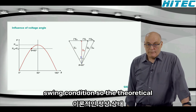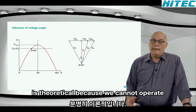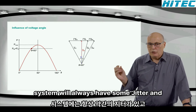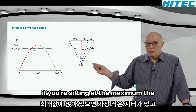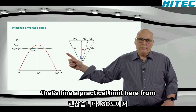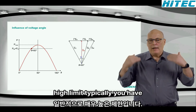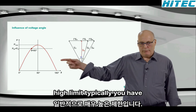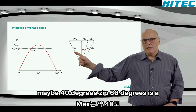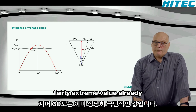So the theoretical steady state limit is Pmax. Obviously, it is theoretical because we cannot operate there, as there is no tolerance. The system will always have some jitter, and if you're sitting at the maximum, with the smallest jitter you're going to slide down the other side. That's why a practical limit is shown here at 60 degrees. 60 degrees is a very, very high limit. Typically, you would be operating at around maybe 40 degrees. 60 degrees is a fairly extreme value already.